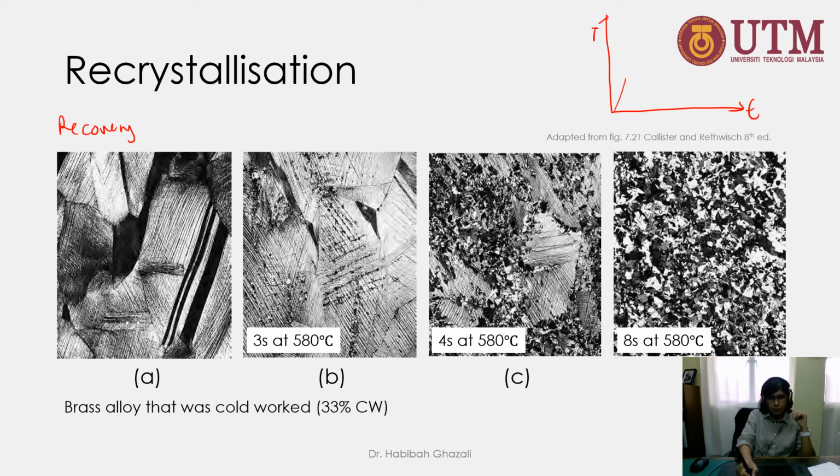It has gone through recovery from room temperature to 580 degrees Celsius. After recovery at this point, there are a lot of tilt angles inside this grain. You can see the grain boundary and the low angle boundary inside this grain.